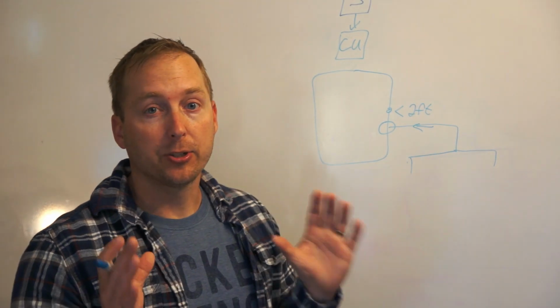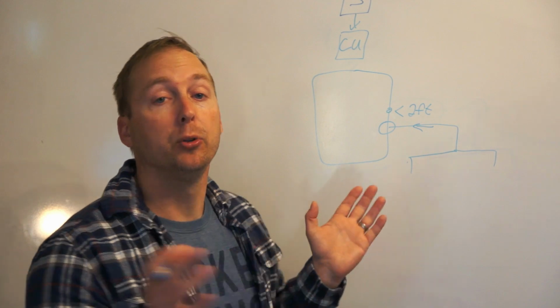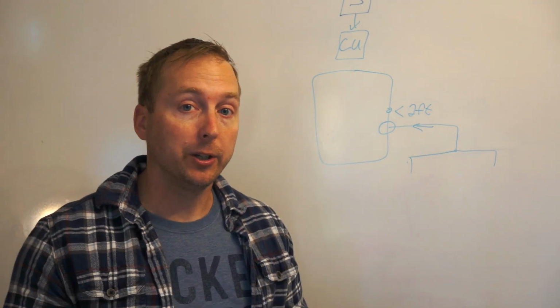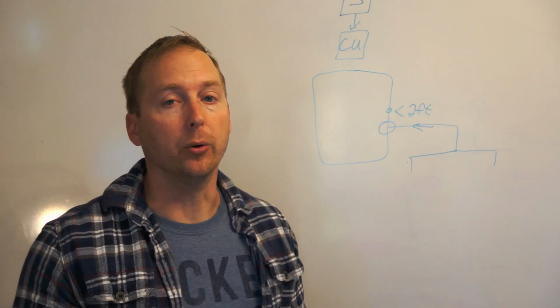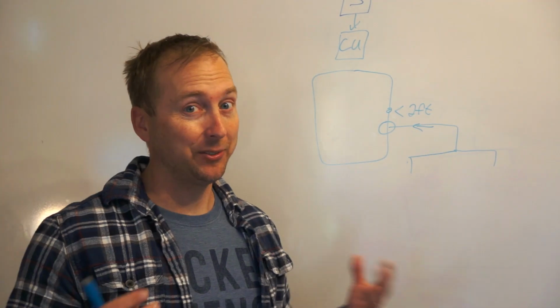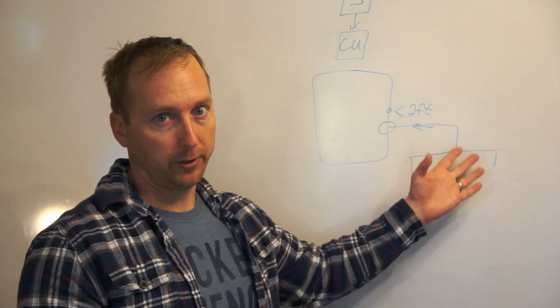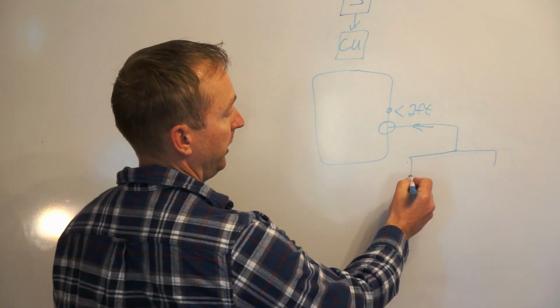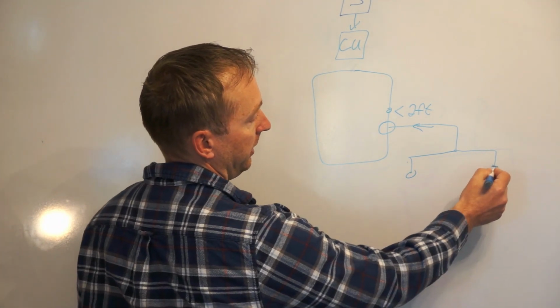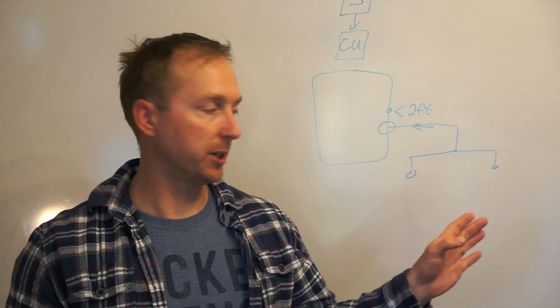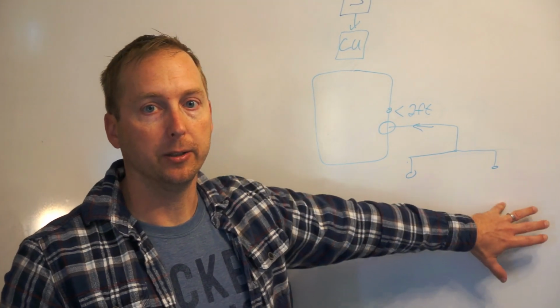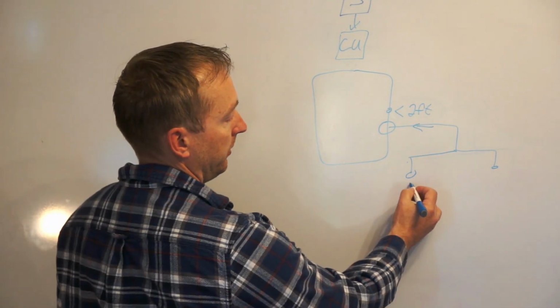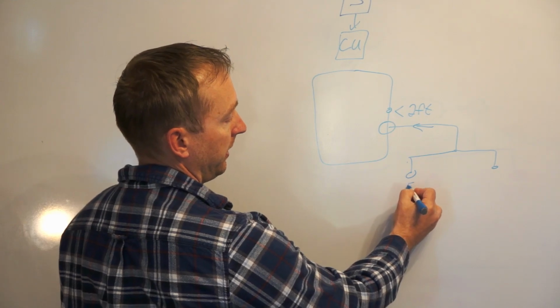So we're going to ask our sensor to move left and then move right. And why are we going to do this? Well, we want to know which direction gives us the most room to move. And from there, we get 2 sets of data. We get a measurement here and a measurement here. So we're taking a measurement from the left and a measurement on the right. Let's say we look left and we get 5 feet.